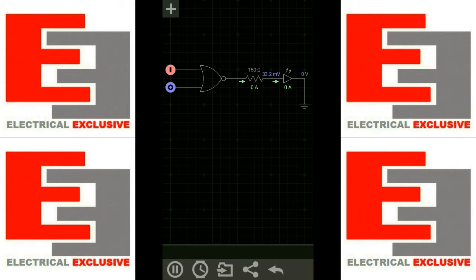Now if I change the first logic source to state 0 and the second to state 1, you can see the output is not available, that is the output is 0. And now if I flip both the logic sources to state 1, you can see the output is still not available. So for the NOR gate, the output is available only when both the inputs are low.